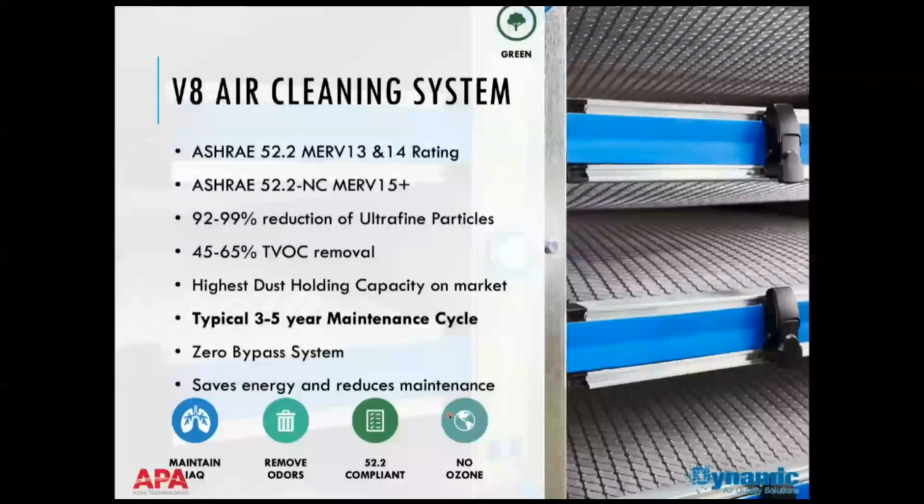Typically, we see a 92 to 99% reduction of ultrafine particles versus outdoor air levels in a building. And again, some of the mechanisms that I'll get to help us have an enhanced ability to do that versus a passive filter. By taking out those ultrafine particles, we're also taking out the gas phase contaminants and odors that are absorbed on them. So we're putting a pretty nice dent into the odors and gas phase. Again, we make carbon systems for museums and people that need carbon. Most people don't, but it's nice to have a little bit of gas phase removal. This system has the highest dust holding capacity on the market by an order of magnitude, and that means a lot less maintenance and a lot less energy.